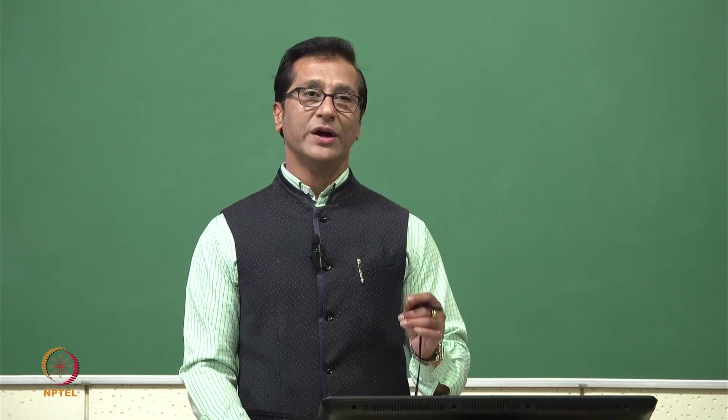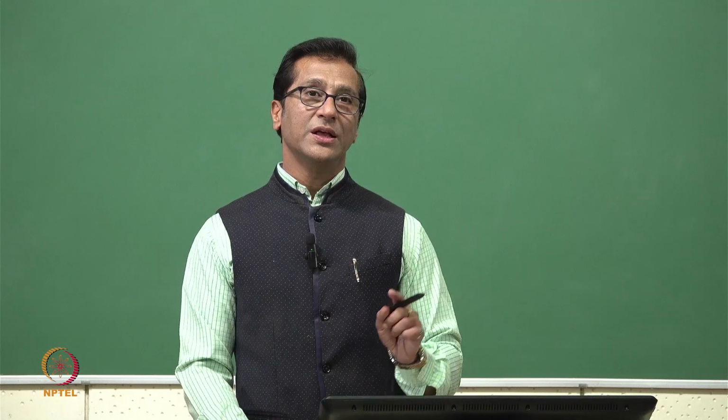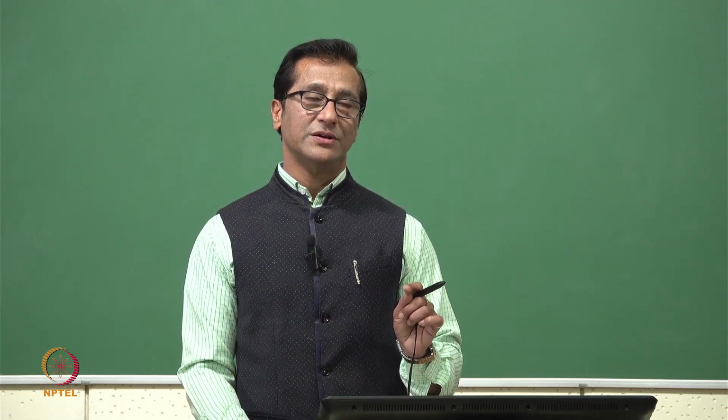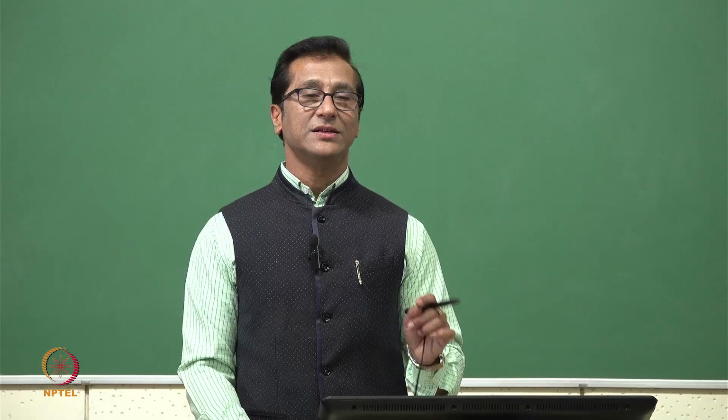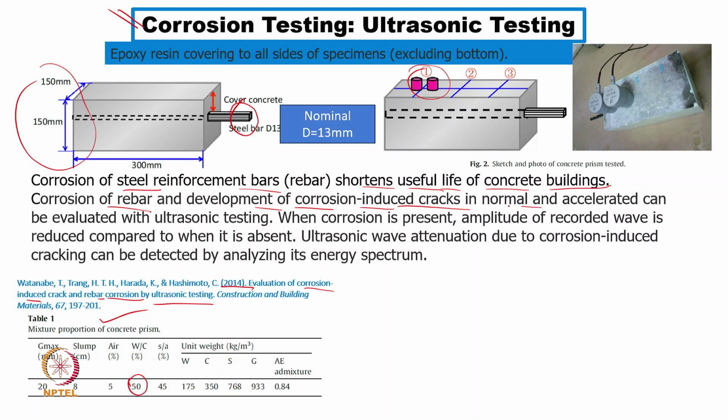So, if we are able to find out those cracks, it is not only the rebar corrosion, even how the passage happens, whether concrete is getting fractured or getting some sort of cracks, that also needs to be detected. So that's why we say induced cracks in normal and accelerated test, we can use accelerated test, and then we will try to figure out using the UT.